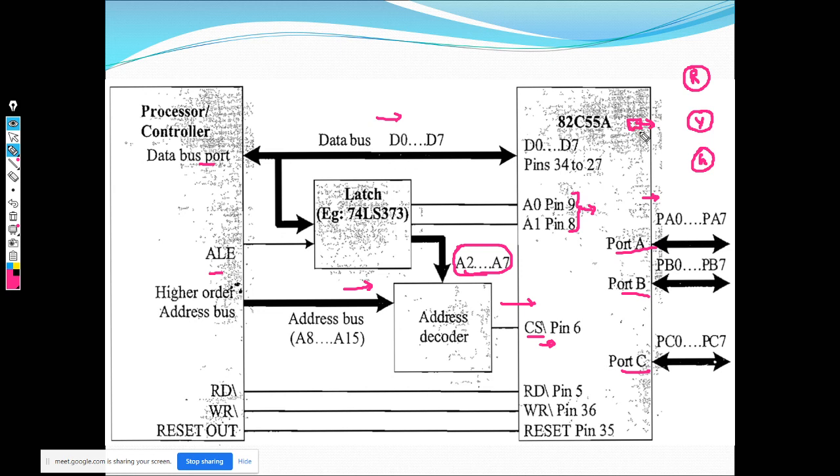But your microcontroller will only have one port coming out of it, because it's a very simple microcontroller you're going to use for traffic lights. Now you're going to use this 8255, and you're going to have three ports here: port A, port B, and port C. So you can say port A lights on, port B lights on, port C lights on, controlling it using the 8255 chip. Basically, with one port, you're multiplying it into three different ports. You're extending the IO capability. Any questions, guys?